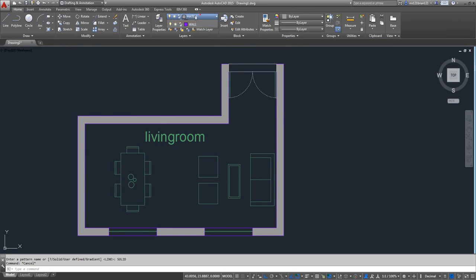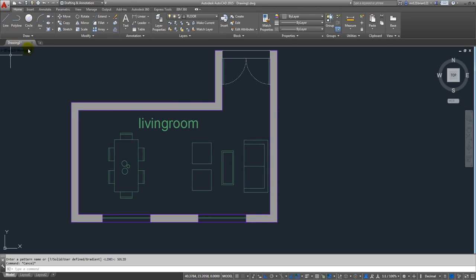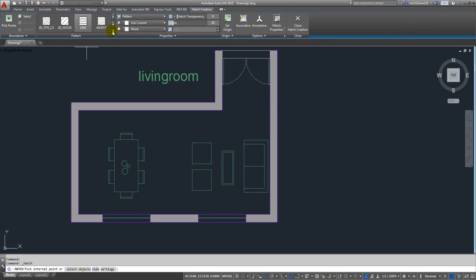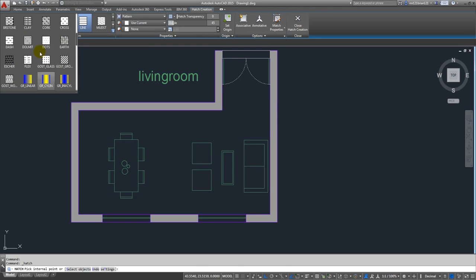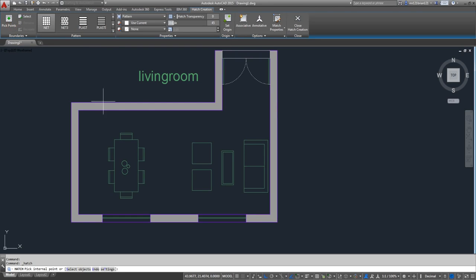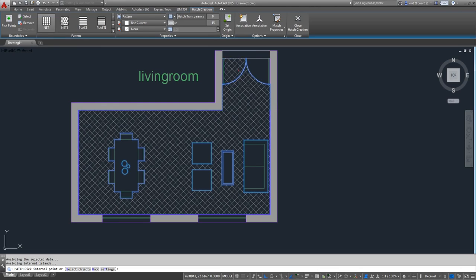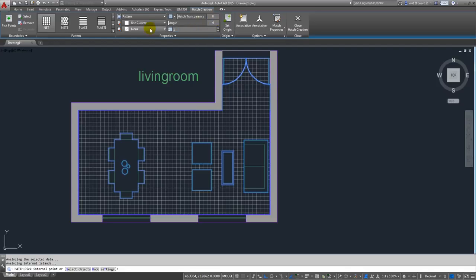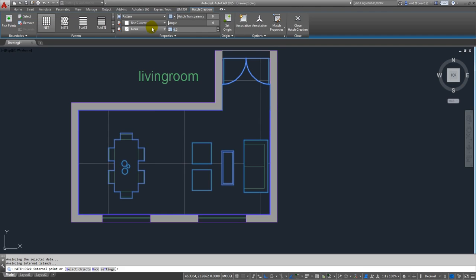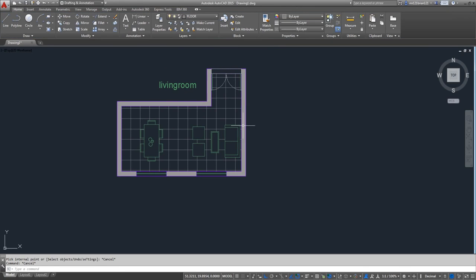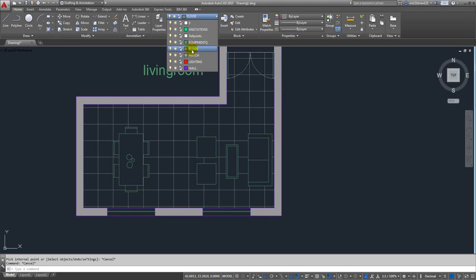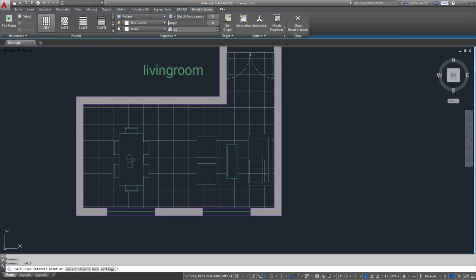We are going to also use hatch for example, our floor. I'm going to first move the text outside so we don't mess it up, and we are going to use for floor. In this case, we can use, for example, net for this floor. We press right over there, angle 0, size is going to be 2 by 2. That's our floor.